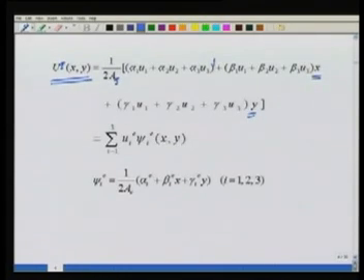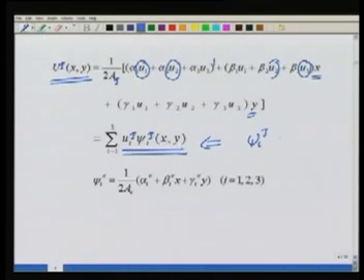We would like to group all the coefficients or all the monomials multiplying U1 together, all the monomials multiplying U2 together, all the monomials multiplying U3 together, and rewrite my U in the element tau in terms of the values of the function at the 3 nodes into some polynomial psi I. Psi I tau is equivalent to what we know as our element shape function Ni tau.